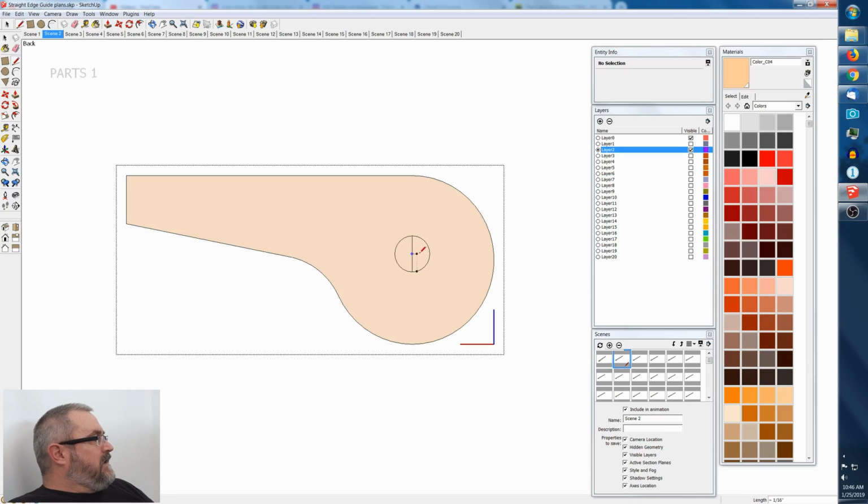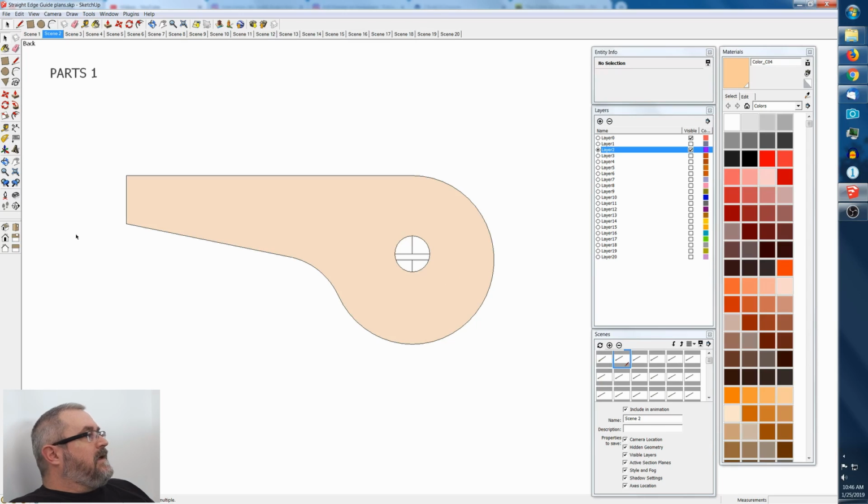And I'm going to reposition it in the screen here, and what I need to do is open the part and add lines to it on this side because I'm not working. I could have reversed it and used the lines that are on the other side, but I'll add these quickly here. And these are the pivot point and the center of the circle for the cam. And I need to add these to the model so that I'll have points that I can use for the dimension tool. The dimension tool in this is kind of strange in that it will not latch onto certain things. You need to add points and lines and stuff like that so that it will do it.